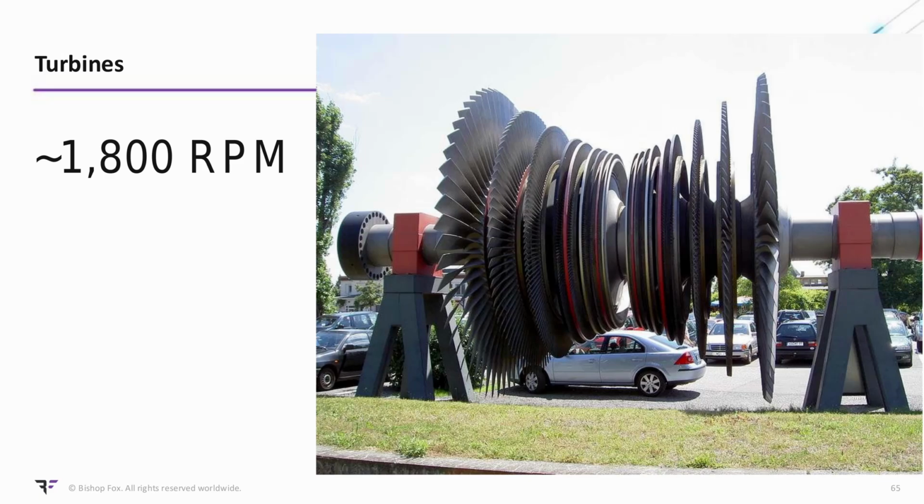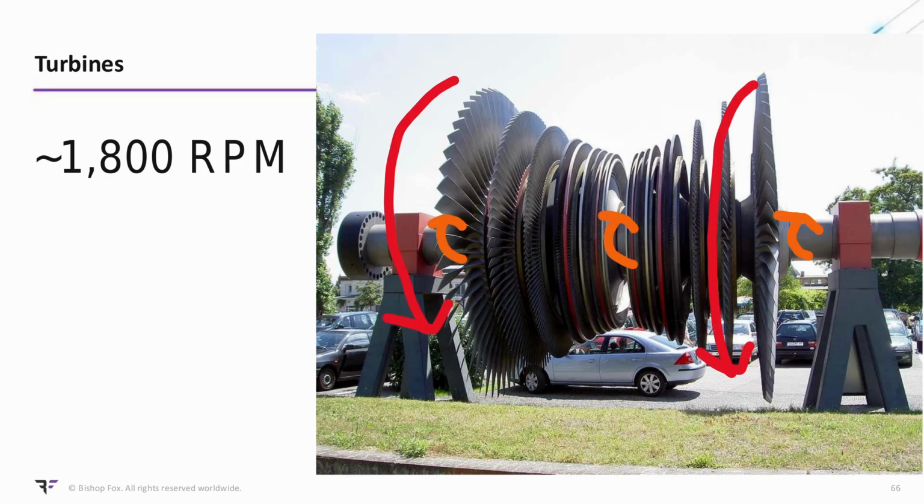And so suddenly, if you were to sever that wire and it's no longer able to accept the electrons, you're going to get this intense torquing force on the turbine that's spinning at something around 1800 RPMs, right? If you're lucky, this will damage the turbine. If you're unlucky, it will catastrophically fail.